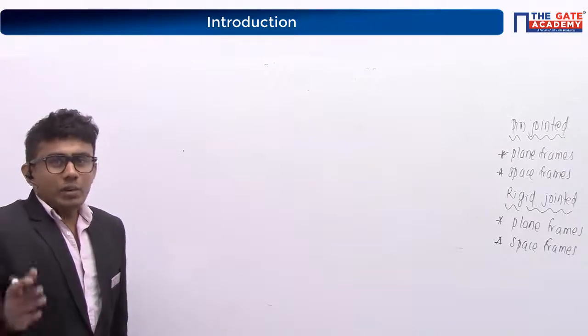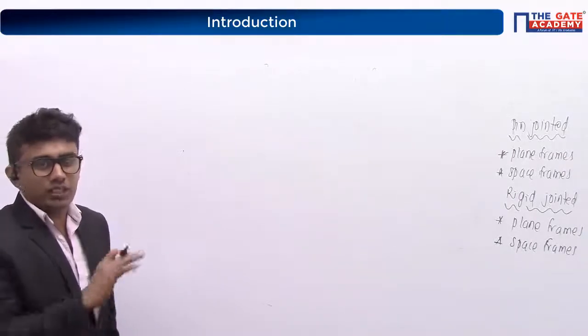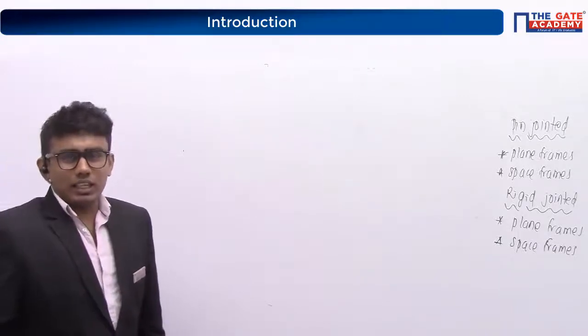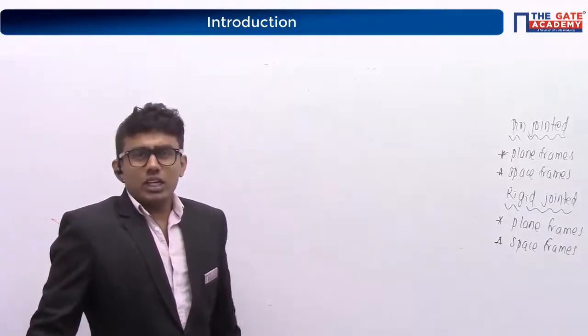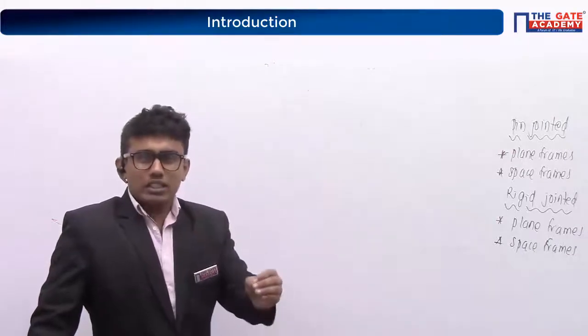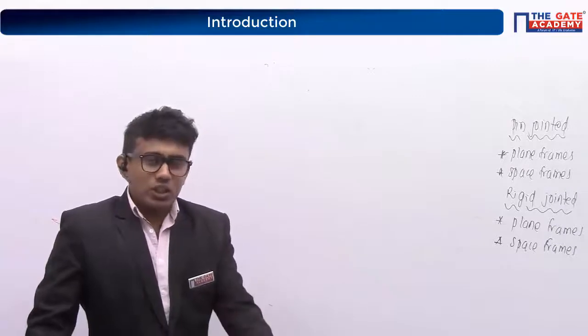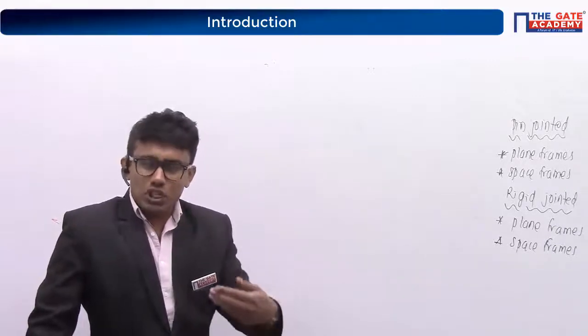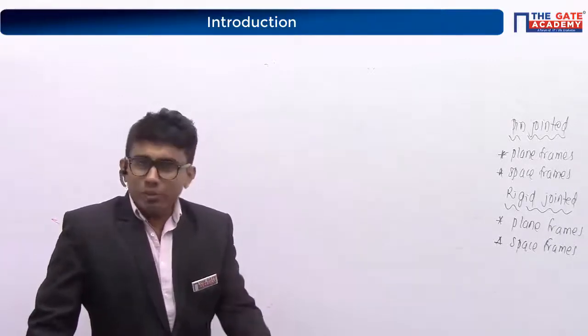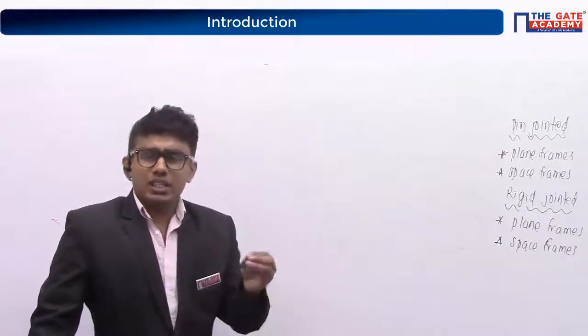Fine. We will be writing the definition, so writing the classification there. Actually, we needed that further. Aditya is asking me to repeat the last point, I think. I was telling that the pin joints will carry the axial forces, and the rigid joints will carry the axial force, shear force, and our bending moment. Okay, you have to remember these two things: our pin connections and rigid connections.